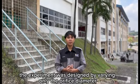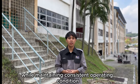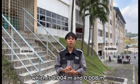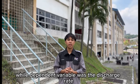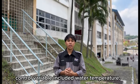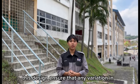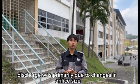The experiment was designed by varying only the orifice diameter while maintaining consistent operating conditions. The independent variable was the orifice diameter, which is 0.004 meter and 0.008 meter, while the dependent variable was the discharge rate. Control variables included water temperature, tank geometry, measuring method, and head measurement procedure. This design ensured that any variation in discharge was primarily due to changes in orifice size.